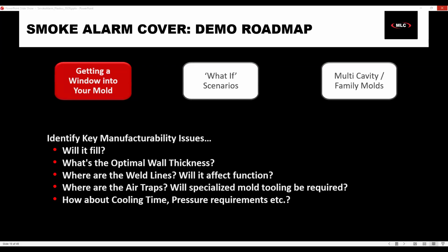So it's predicting the fill pattern based off of where we just selected that location. You do have to have the mesh already run for this to be an option. It'll be grayed out, as the little tooltip says. But if I go ahead and click on it, because I do have my mesh here, this is not a full calculation, but it's a pretty good estimate of what the fill is going to be.